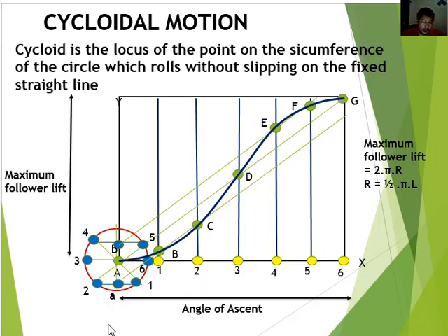The second method: divide the circle into any number of equal even parts. Now we can look at this illustration. This one has 6 parts. Project these points horizontally on the vertical center line like this.